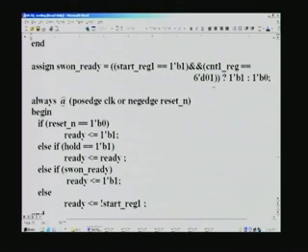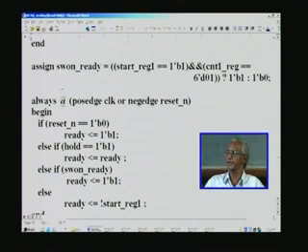And so at this stage we can allow the host to write data into the other RAM whose value has already been processed, and that is what we are doing here. Only when this condition is satisfied. If it is not satisfied, ready will get the inversion of start reg, and for example if it is 1, it will not make it ready, and that means there is no start signal.